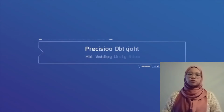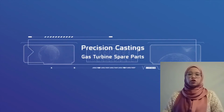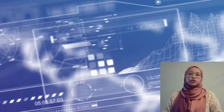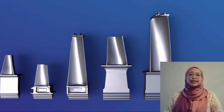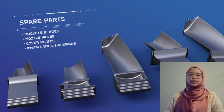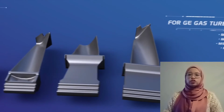Blades are also produced through the investment casting process using nickel-based superalloy. For investment casting, sometimes called lost wax, the pattern is made from a wax or plastic that has a low melting temperature. In the process of casting, investment is divided into two stages.